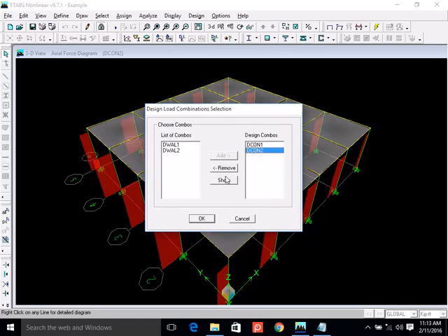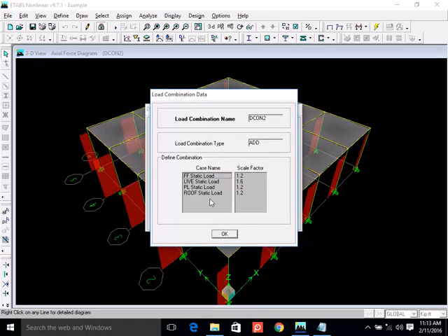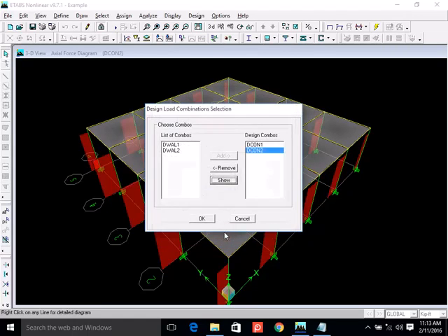Decon 2, show. You will see that for dead load it's 1.2, for live load 1.6, and for the other dead loads, partition and roof, the factor is 1.2. So it's actually 1.2 dead load and 1.6 live load. You will see Decon 3, 4, 5, 6, 7, 8, 9, 10, 11, 12 when you have earthquake and wind loading. Right now we will stick only to these two load combinations which are already included.